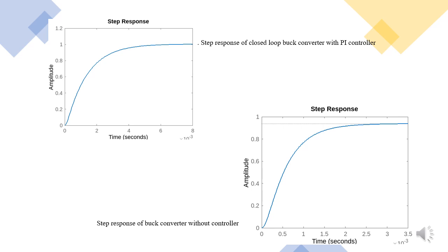In terms of tuning a PI controller using MATLAB, the following general approach is typically followed. Initially, set the integral gain Ki to 0. This means that only the proportional term is active and the controller essentially operates as a P controller. Increase the proportional gain Kp gradually until the desired response of the system is achieved. The response can be evaluated based on criteria such as settling time, overshoot, or steady state error. Adjusting Kp allows for influencing the control signal proportionally to the error.